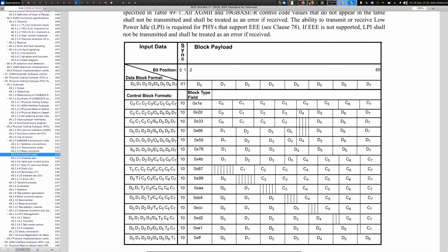You could use like a break, right? You can hold the line in the active state for a while. You can do some timing related stuff. Not particularly all that great. You could send more bits, right? You could send 9 or 10 bits per symbol or something like that. That's a possibility. I'm not sure how good of an idea that is. That's not necessarily a standard thing, but that would allow you to mark some bytes. Another thing that you can do too is if you're using just the lower 7 bits for your data, you could use the 8th bit for framing if you wanted to, or you could use various encoding schemes.